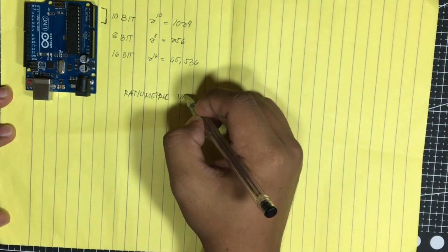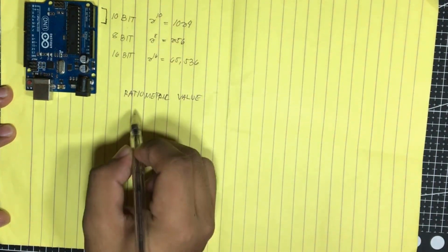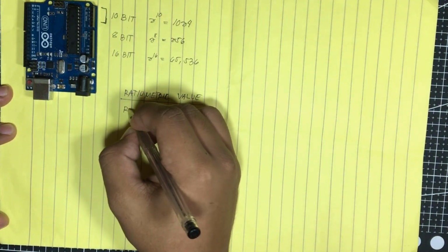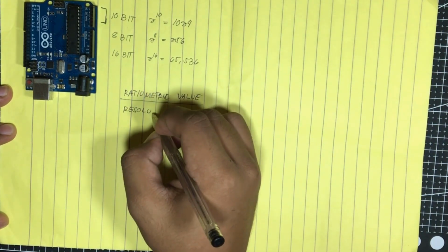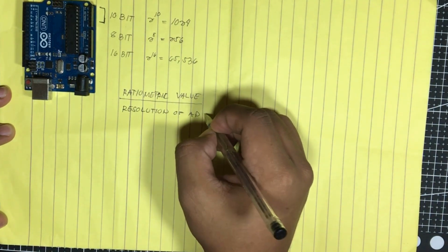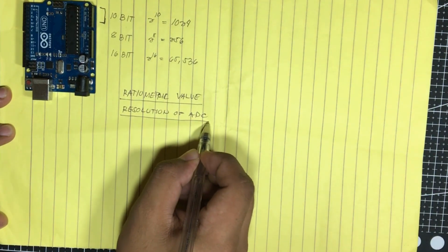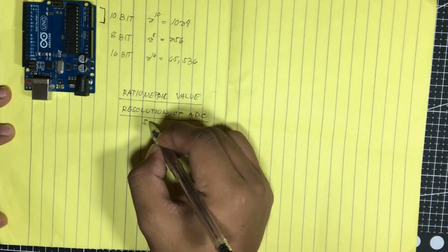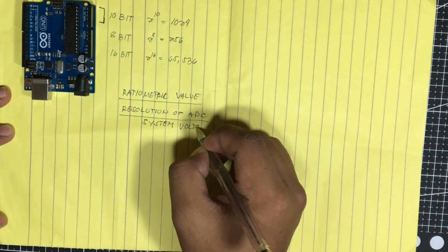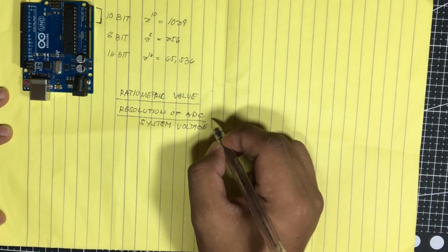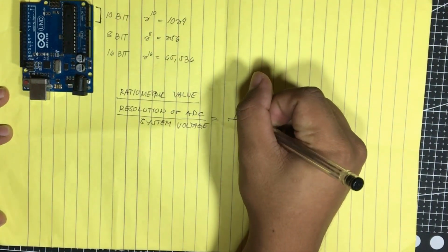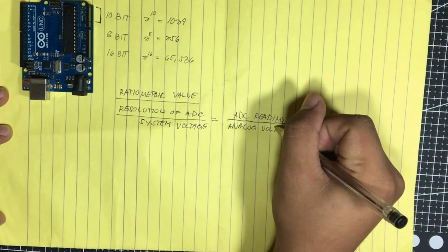The ADC reports ratiometric values. This means that the ADC assumes 5 volts is 1023, and anything less than 5 volts will be a ratio between 5 volts and 1023. The analog to digital conversions are dependent on the system voltage, because we predominantly use the 10-bit ADC of the Arduino on a 5-volt system. We can simplify the equation slightly.